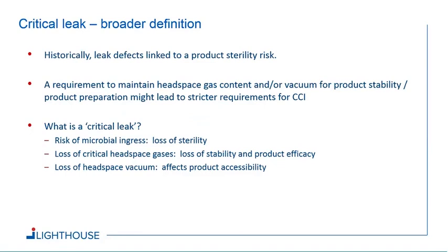Now, historically, leak defects have been linked to a product sterility risk, which is why I think you see, as happened to this particular company, people wanting to link container closure to a microbial ingress test. However, more recently, more and more products have a requirement to maintain headspace gas content or vacuum, for example, for product stability and product preparation, and maintaining the headspace gas content leads to more strict requirements for CCI.